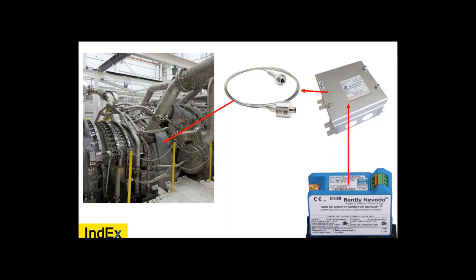If an LED is EX mb protected, free volume is less than 10 centimeters cubed, is it okay for zone? Okay, so that question is off base. It was EX nC, and there would not be an nC light, there would be an ec light. So that question I cannot answer.